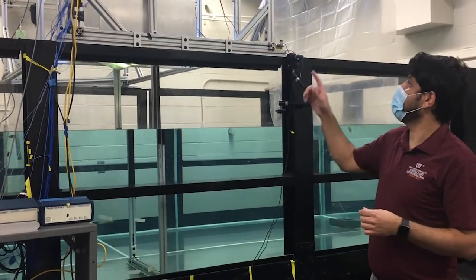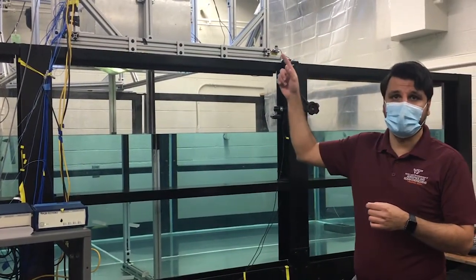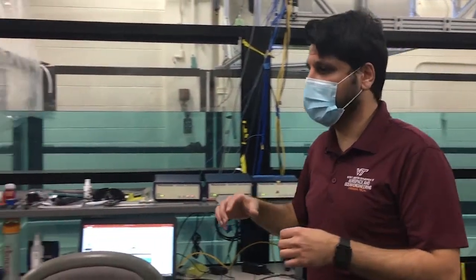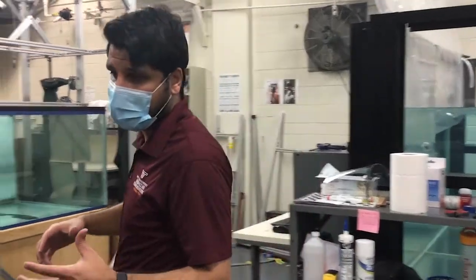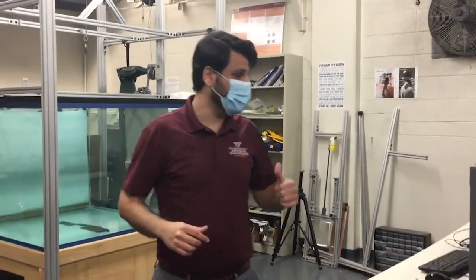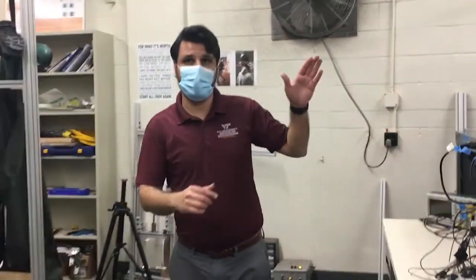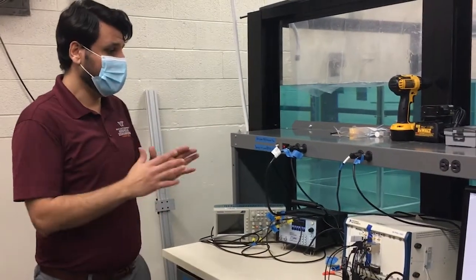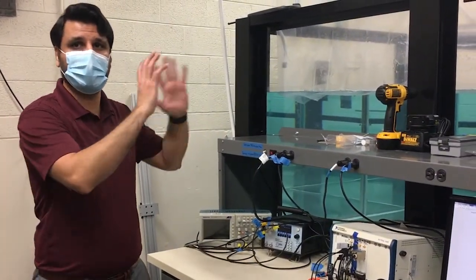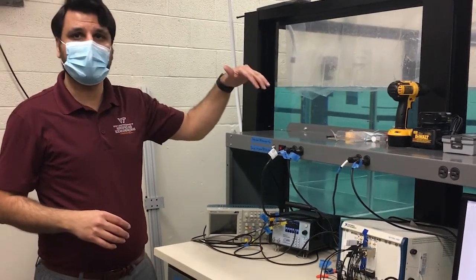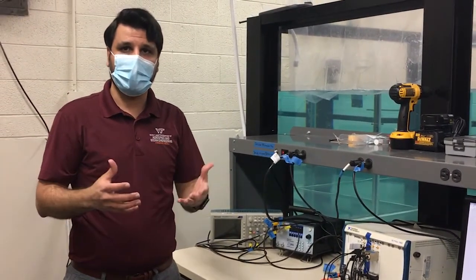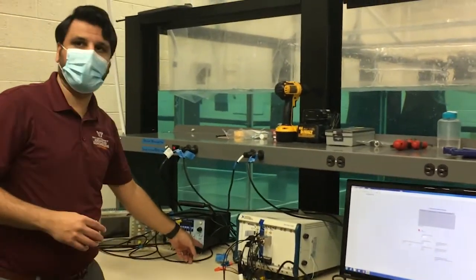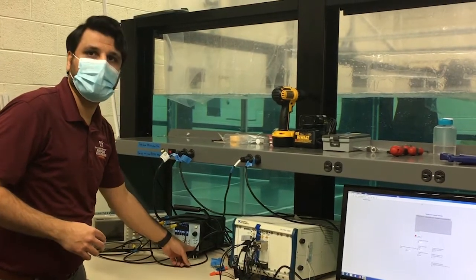Alright, so now the wedge is attached to the electromagnets. So now we are going to use the DAQ system here. So we have a DAQ system, a pulse generator. When I press the button, we cut the power of the electromagnets and basically we let the model release and drop. And at the same time, the DAQ system orders all the instruments, including the 3 high-speed cameras that we have, to start acquiring the data. So get ready. We're gonna drop it after the countdown. 3, 2, 1.